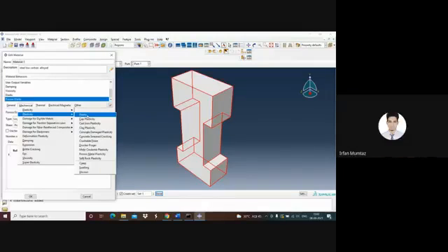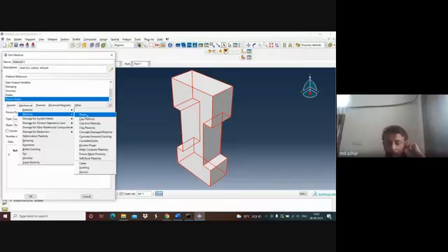You will give mechanical property, that is toughness. No, that is your outcome. Toughness is not your input. You have to give the plastic properties, because when the car gets stuck into the building, it is going to show the plastic deformation. Also it will have to be resilience.